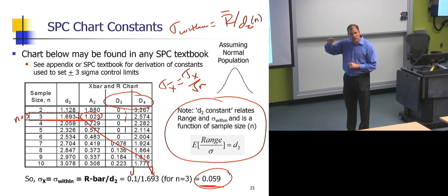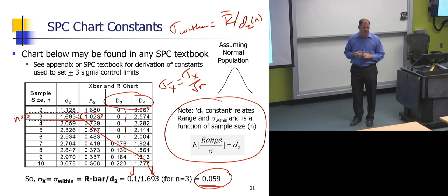I probably have some small between group variation, but it's being folded into the moving range. And the result of that is the moving range is a wider estimate of the inherent variation. If the moving range is a wider estimate of inherent, what's going to happen to my control limits? Conceptually, they start to get a little bigger. That's where they become less sensitive.